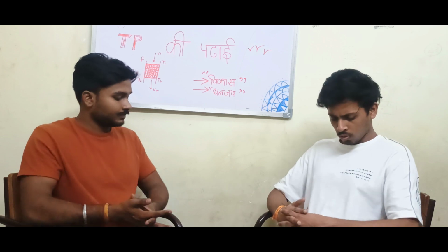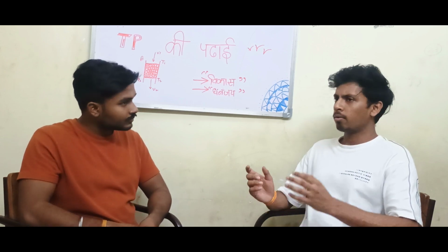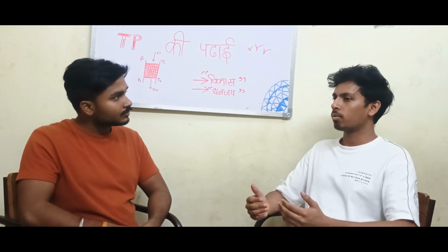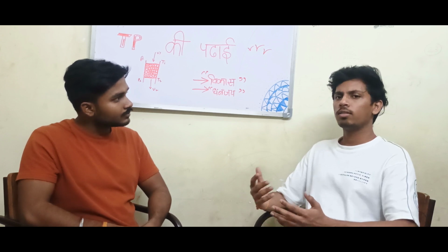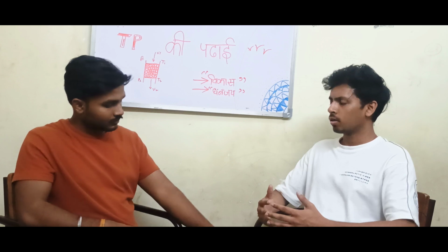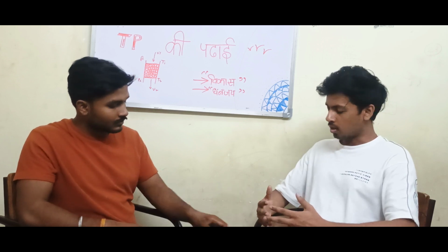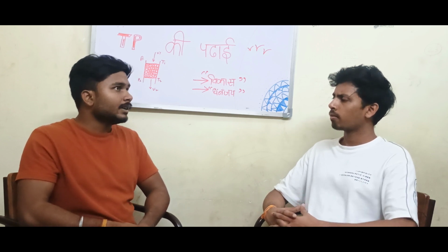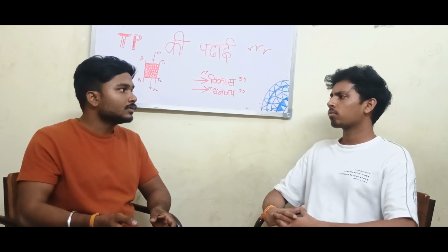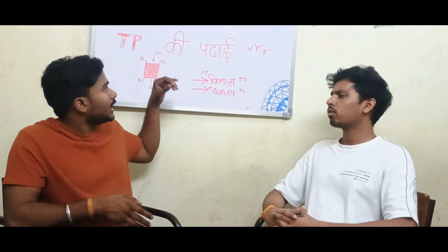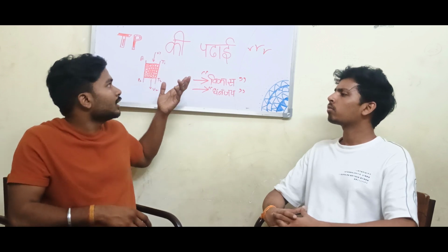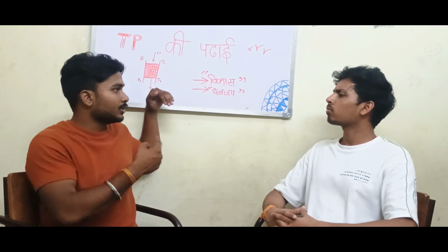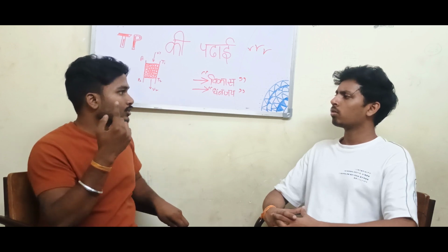Suppose we are measuring through experiments and finding out the mass transfer coefficient. What are the challenges in measuring the mass transfer coefficient in a packed bed column? If you are doing it experimentally, it is quite tough compared to doing it theoretically, because in that column, the fluid coming from inside might have maldistribution, not evenly distributed.